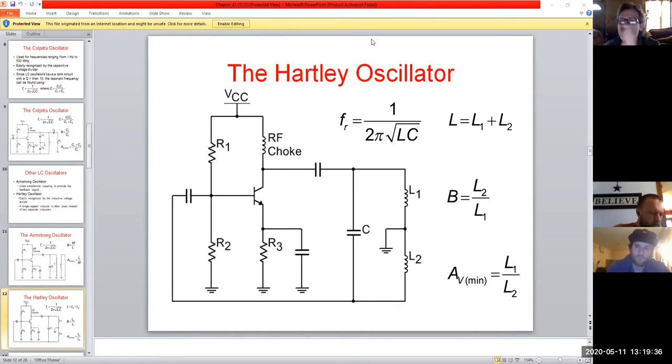So when you do the sweep, you're not analyzing it from a perspective of time, you're analyzing it from a perspective of frequency. Then when you want to switch and say, okay, I want to see this linearly, you have to tell LTspice that, because it naturally defaults to looking at it from a frequency perspective. If you want to find out, let's say, what your output resistance is, well, that is a linear response, not a non-linear response.